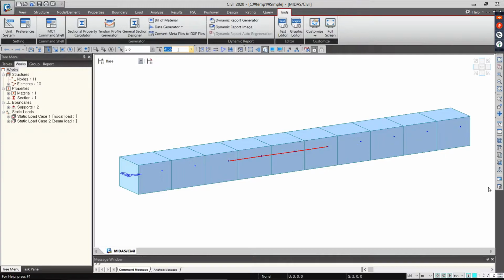On the contrary, if we note the node number or element number, we can select it by entering directly here. So, enter. We can check selected nodes. And then by unselect all here, all elements are unselected. Select all, unselect all.